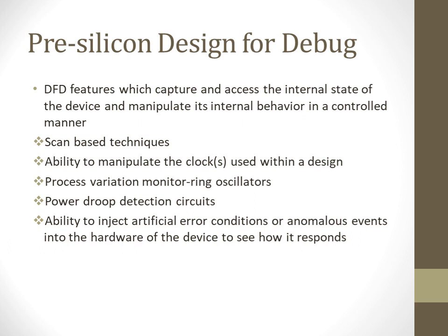This allows the data contained within the storage elements to be serially shifted out by clocking them with some special serial shift clock. Thus, we can analyze the internal state of the storage elements, and we can manipulate these states using some buses connected to the shift registers.